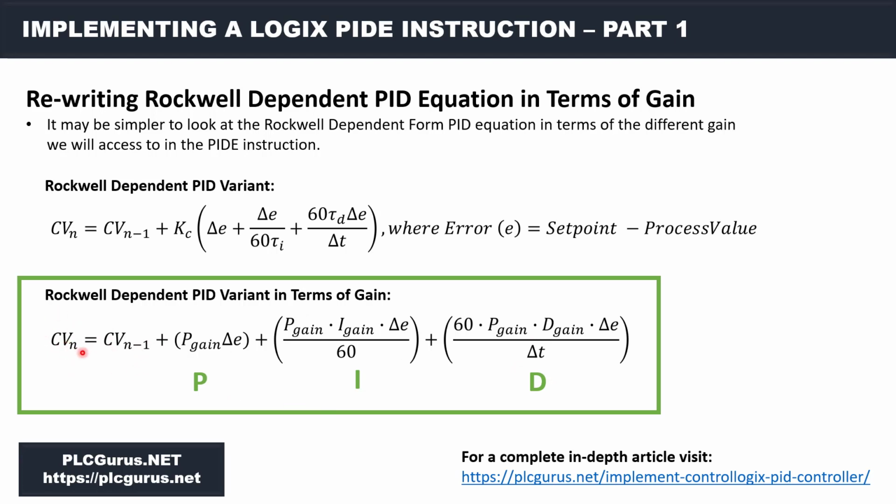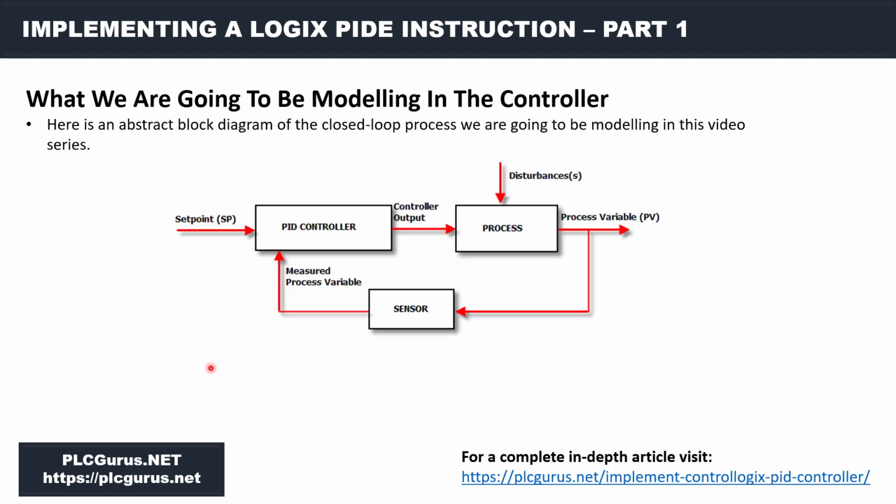And it's doing that every scan. Okay, so that's what it's doing, and then it's making a change. We're going to be seeing the impact of that change via the process variable, feeding that back, checking the error, computing a new value, and it's doing that continuously. Okay, so that in effect is what PID is and continuous measurement is, and closed loop feedback control.